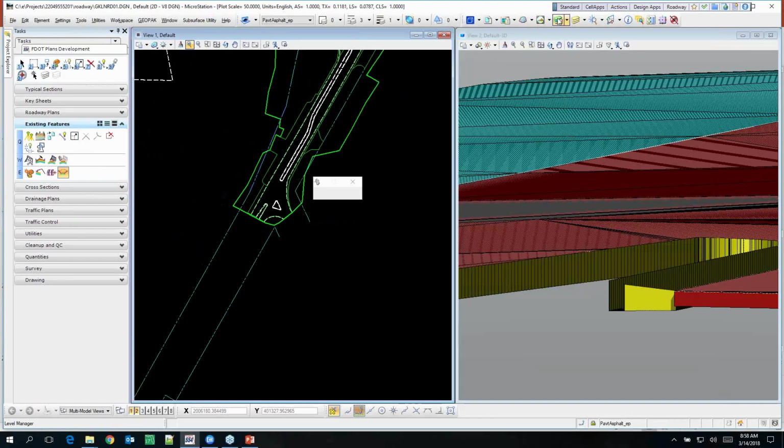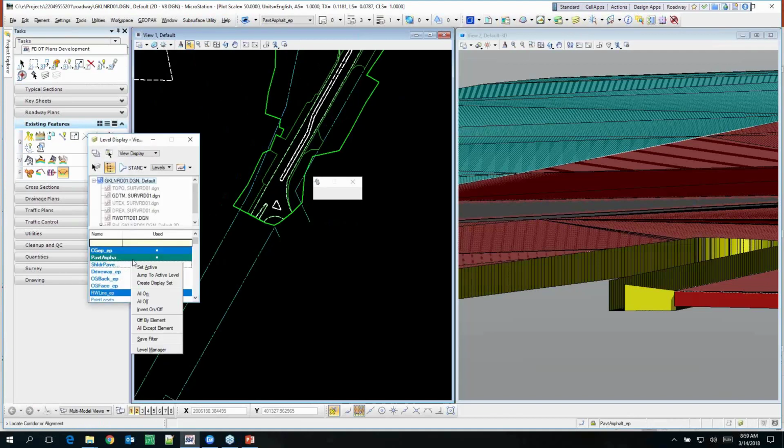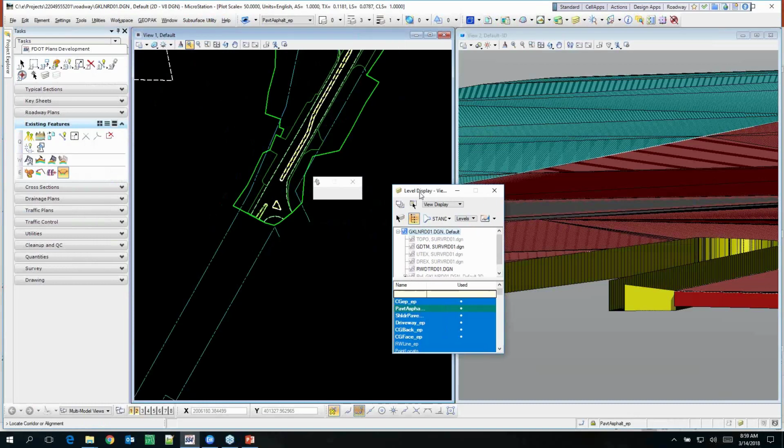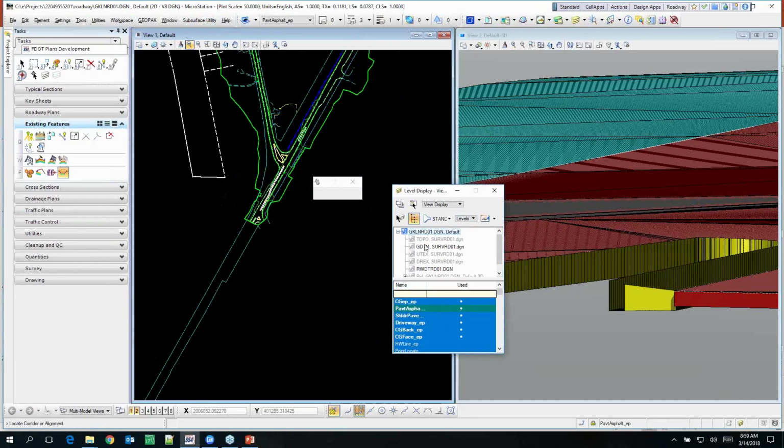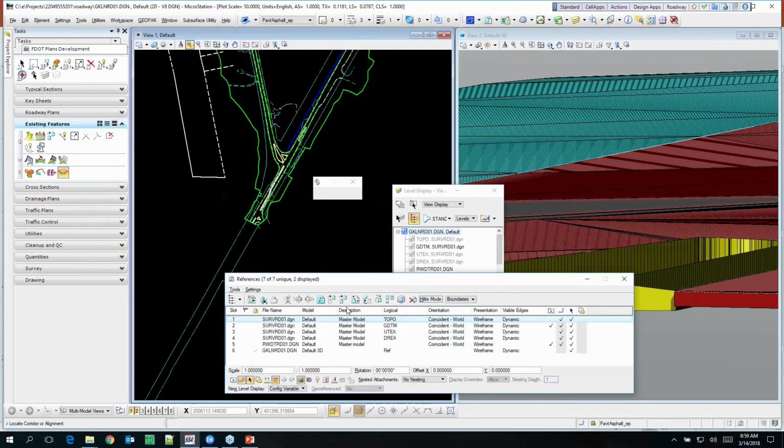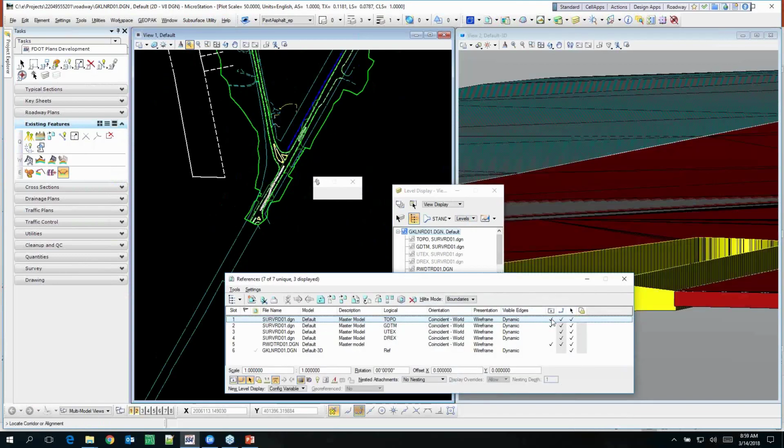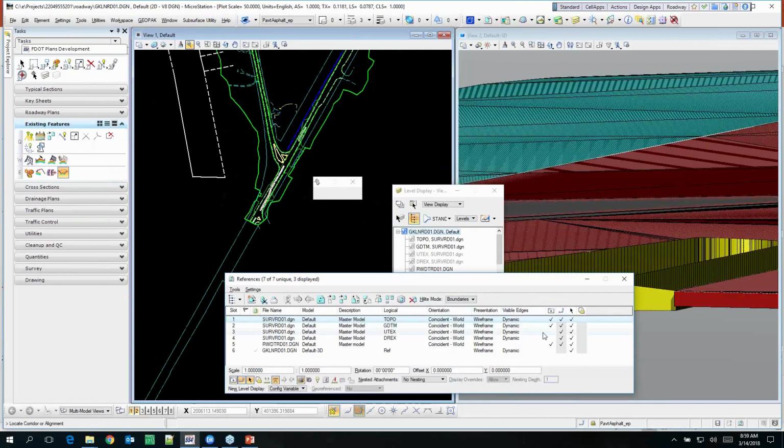it might help if I have the alignment showing. No, in this case, what I would do is create a line out there somewhere that you want to cut cross sections about. Usually it'll be a baseline. Yeah, that's why I was going to show the alignment. This one you just do the alignment. There's a baseline out there somewhere. If there was, it would be in the topo file. Yeah, there's one in the topo file. The topo reference.